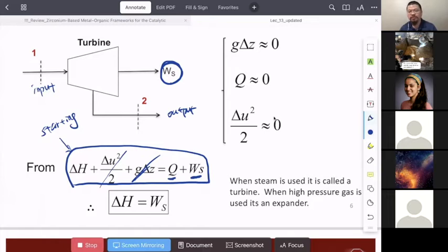This is how we are going to achieve the maximum efficiency as proved by Carnot, right? So here, for this ideal analysis, the adiabatic process will have zero heat exchange, right? The zero heat exchange is for the turbine together with the input and output with the surrounding.